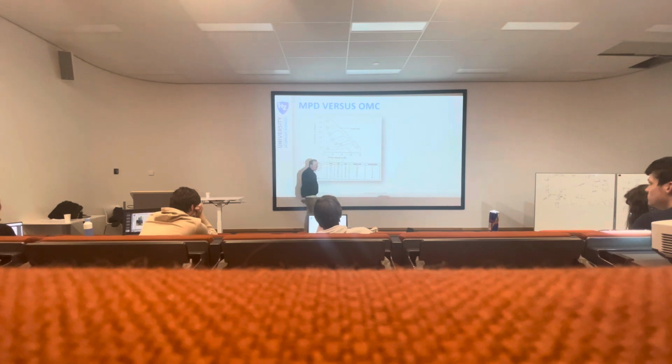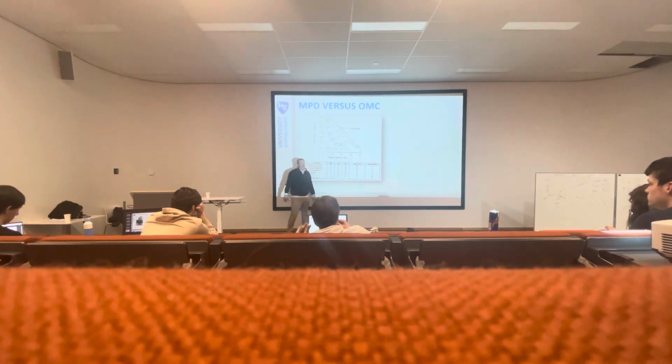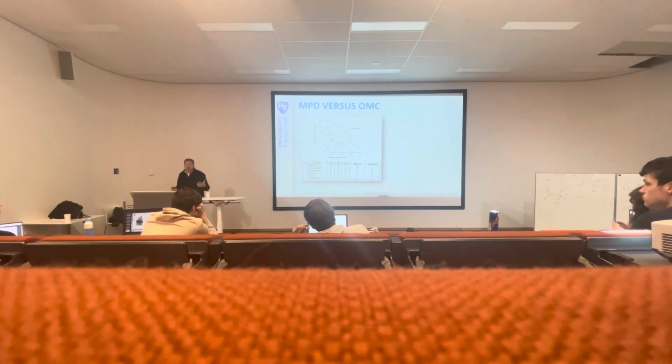You're still in a range that you're good, and with sand, you have to be more or less exact at the top. Otherwise, the sand is not good. That's why it's very crucial when you have to do compaction of sand, you have to do it with nice weather. Actually, for civil engineers, it should always be nice weather.